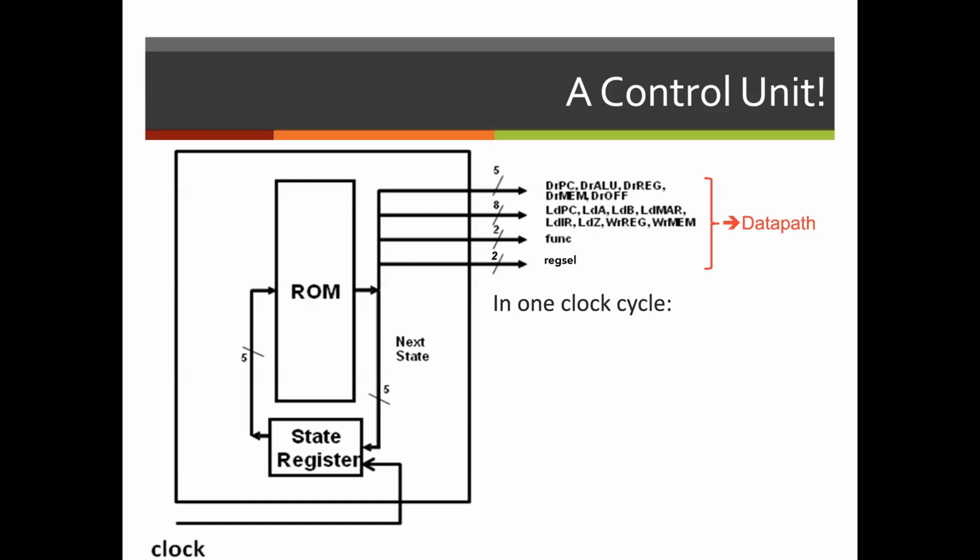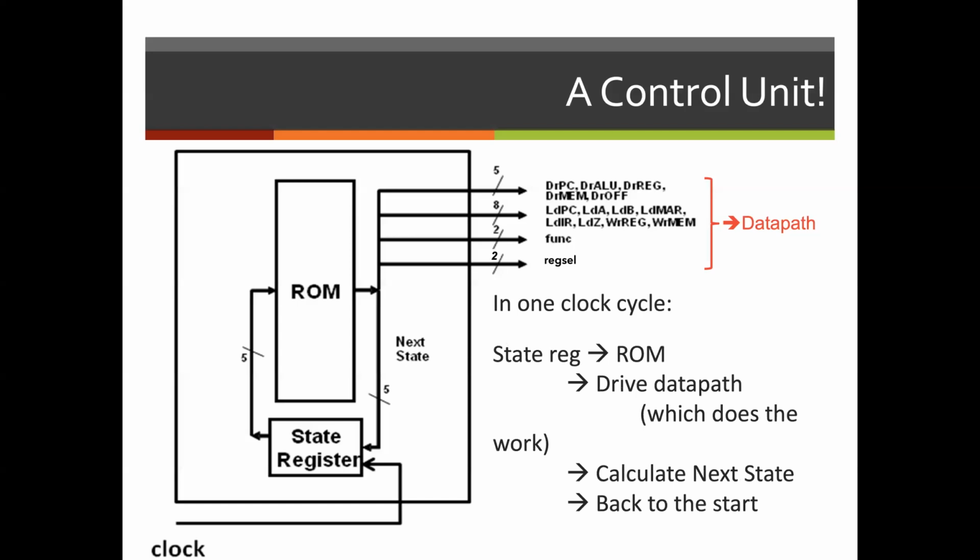So we want to make sure that all of our appropriate load signals that are coming out of our read-only memory serve as masks for the clock signal. And this allows for appropriate determination of other elements that are required. And so it provides for calculations for next state, or if we need to go back to the start based on the clock cycle.